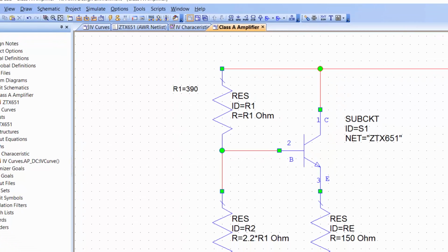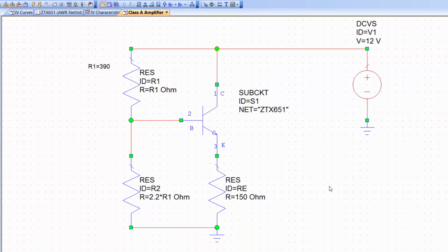Now here's the thing, when it comes to biasing the transistor, you're working at DC, and hence we didn't really need the capacitors shown in the schematic. But if you need to put an AC signal into your transistor, then you will need to have capacitors, which are open circuits at DC, to avoid your signal affecting your bias network. So let's put those in.